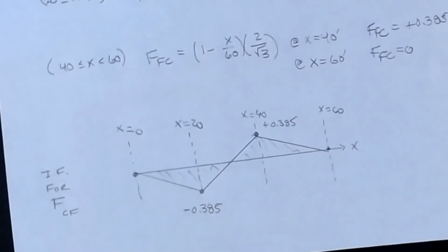Now, unfortunately, trusses are kind of long. You have to resolve the trusses for however many panels you have, and for big trusses, this becomes very complex. But in general, it's a very straightforward process to be able to calculate influence lines for trusses once you get the load spread out. Everything else is the same as beams. It's just that we have to be able to get that one kip load spread to the ends with that offset. And that's the trick for influence lines for trusses.